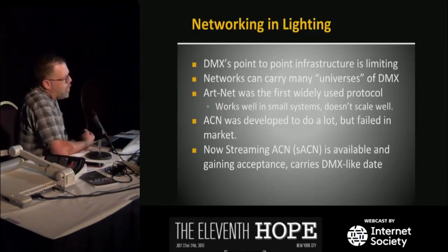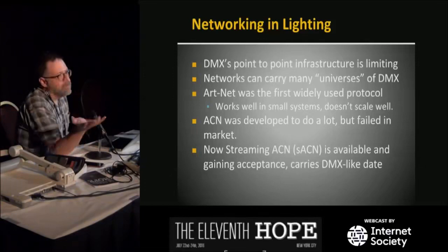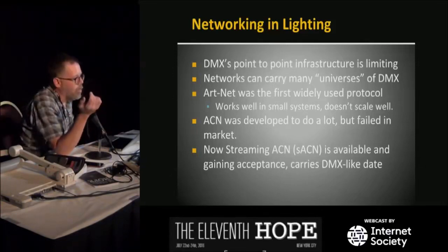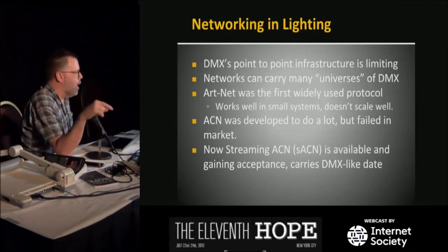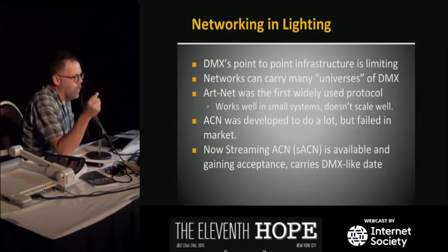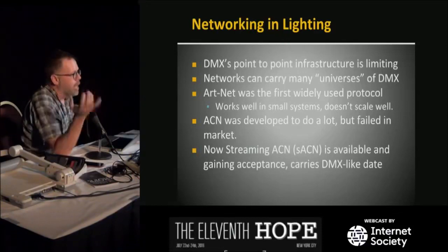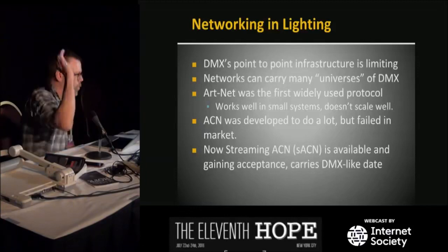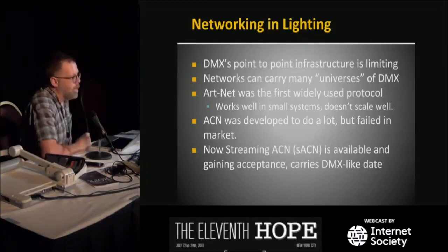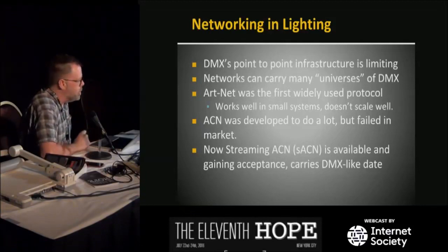And these are used in a lot of cases. In here with a few lights, maybe you don't need it, but if you're doing a big concert, where with the old DMX stuff you would have had 50 cables from your console up to the lighting truss, that's a pain to put in and out every day and deal with. So now we can run one network cable and carry all that same data up there. Practical reasons like that are what started the adoption.